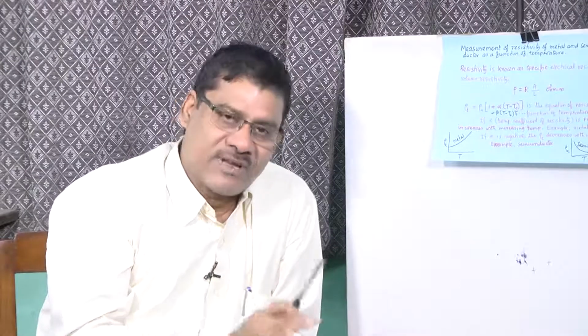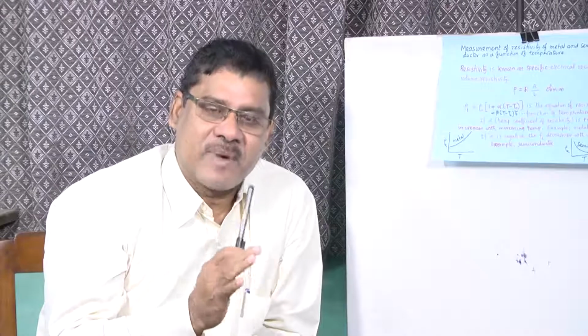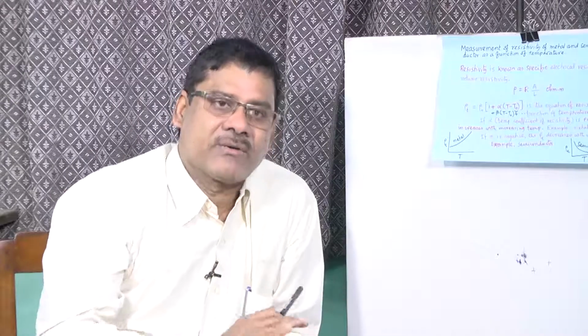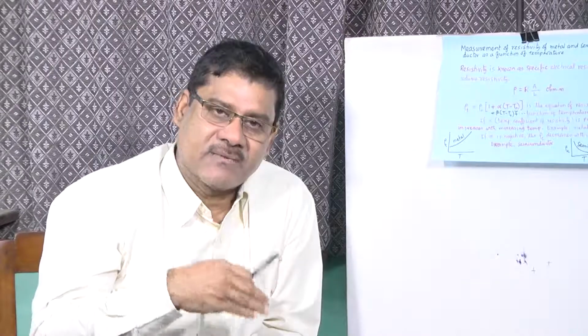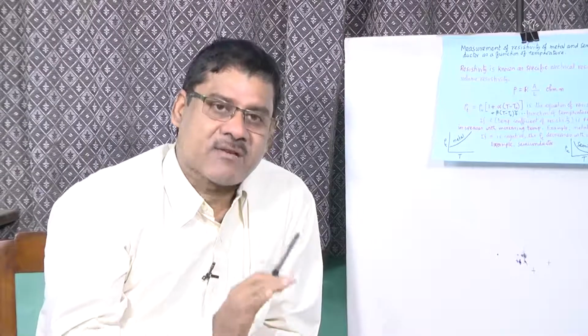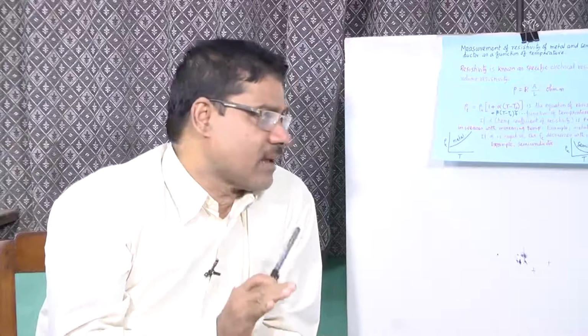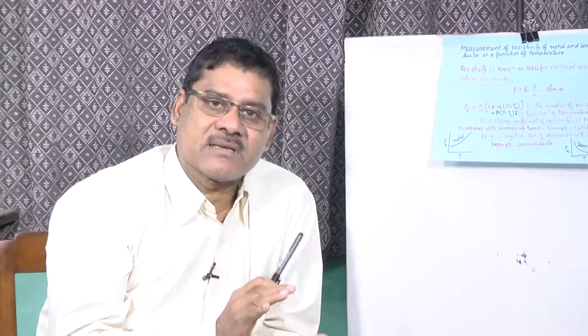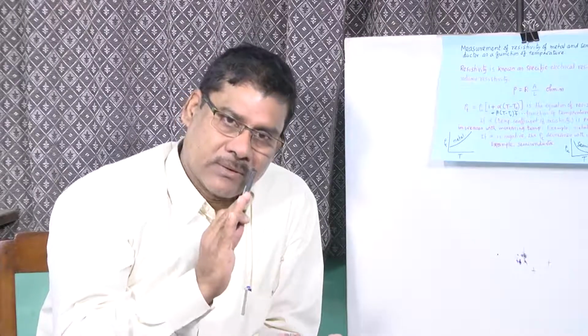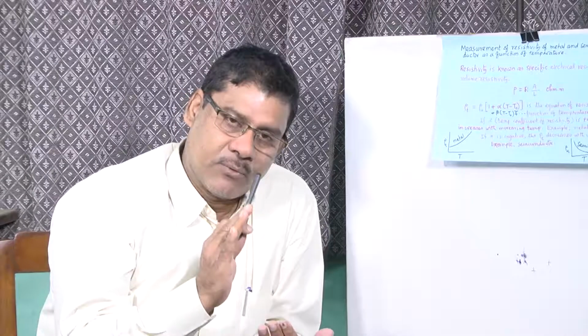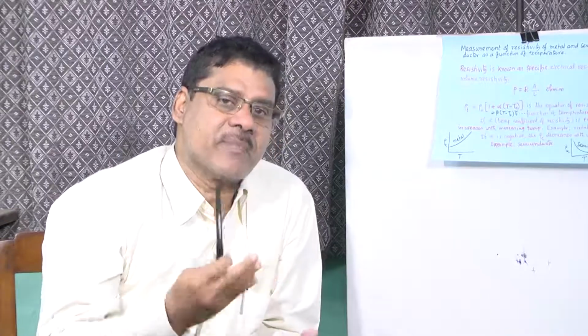Generally in case of metal it is positive, so with increasing temperature the resistivity will increase. In case of semiconductor, the temperature coefficient is negative, so the resistivity will decrease with increasing temperature.